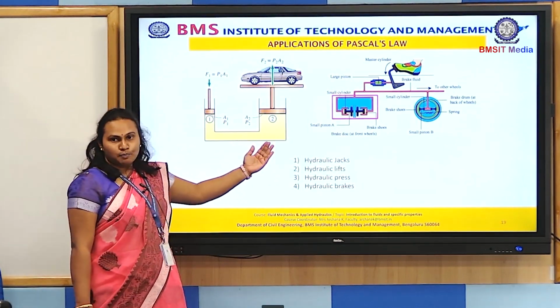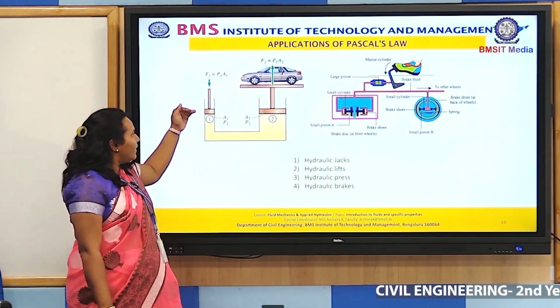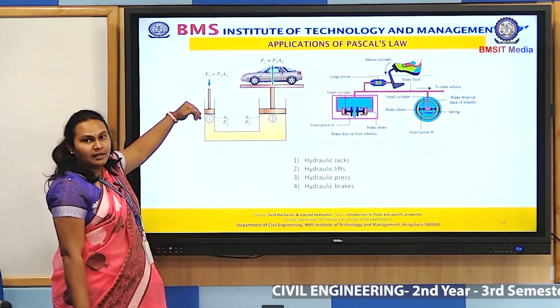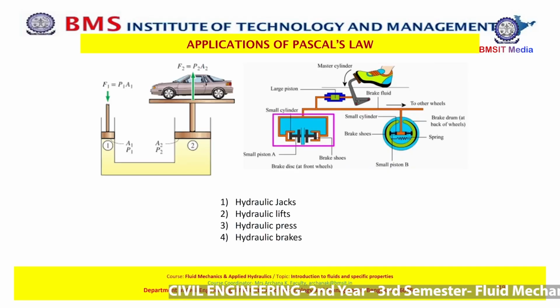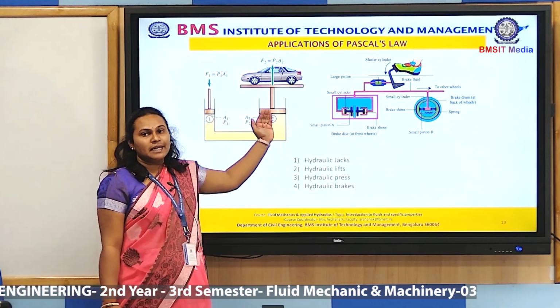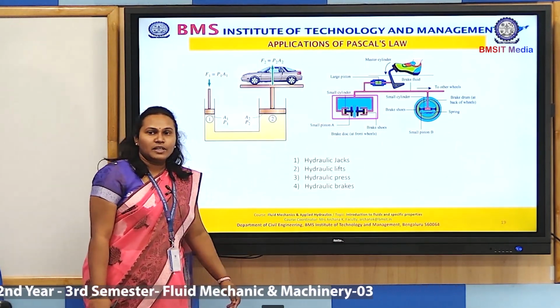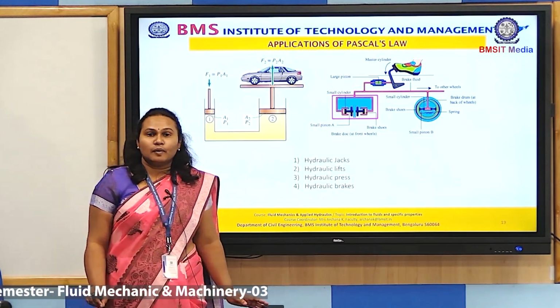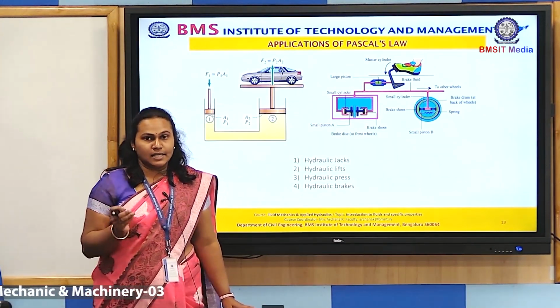and these two act like pistons, and when this force is pushing the oil or the fluid filled here, automatically the fluid pressure in this direction will increase. Please note, this can happen only if the pressure intensity in all three directions is the same.